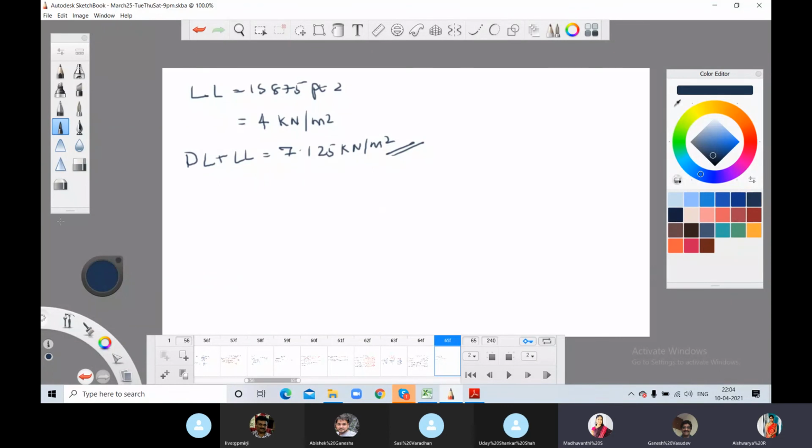Madam, here you are not considering the finishing load? No, the finishing load is not considered. This is just basic load transfer. So we are not considering the extra loads like finishing loads or partition load. That won't be coming under basic load. That will be coming under normal load calculation. Okay, this is fine, just basic. So here we are seeing only the basic load transfer techniques, sir. We are just explaining how the loads are getting transferred. Floor finish load and everything will be considered while doing the slab design. Okay, sir.